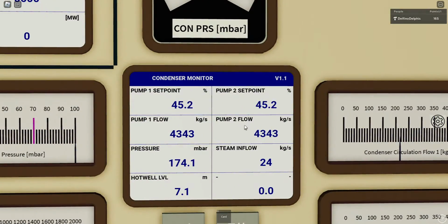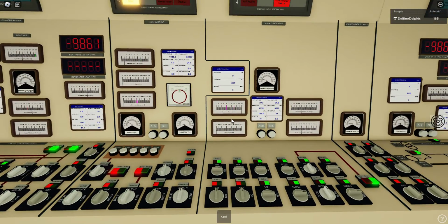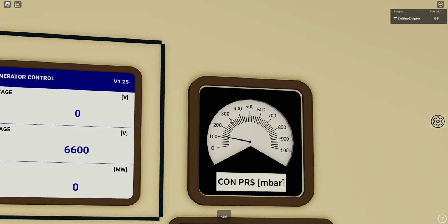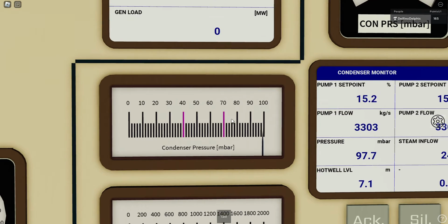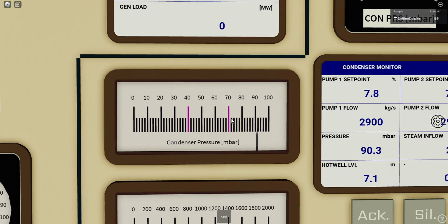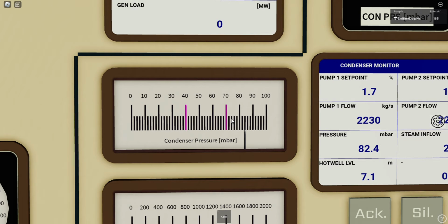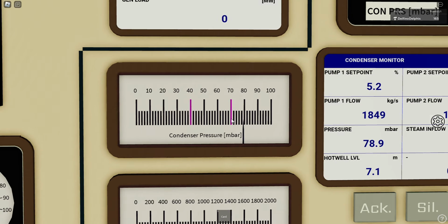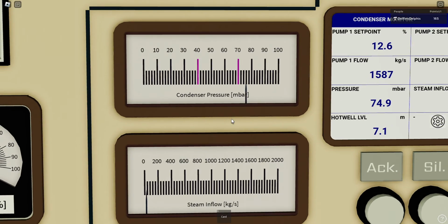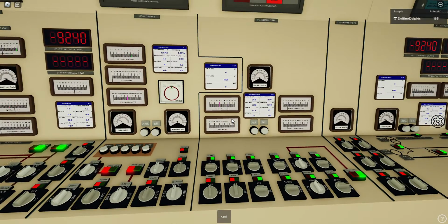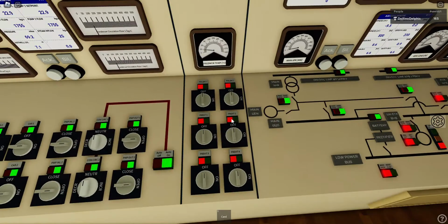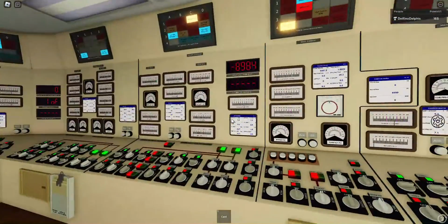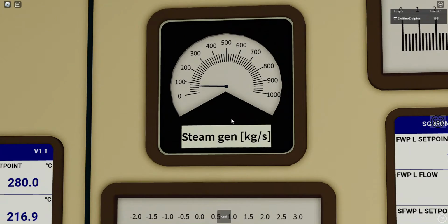The auto control will now set up the circulation flow to condense the pressure to the desired level. So this is now happening, and we are pretty much set up at this moment. Okay, of course we should also enable preheaters. There are 4 of them and 1 polisher. This should increase the steam generation rate.